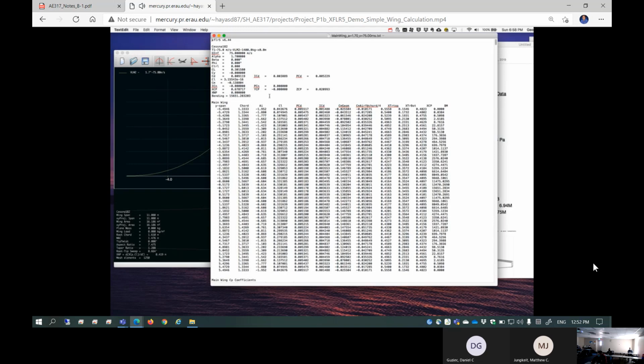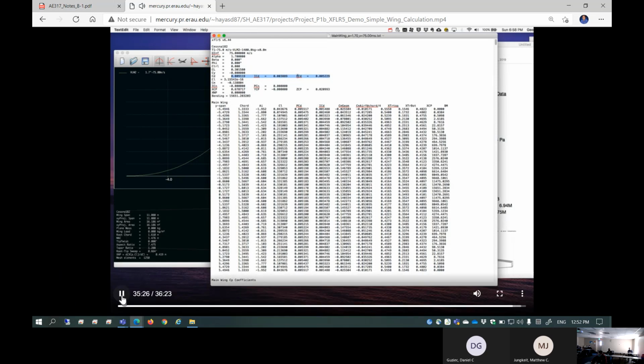And so I have similar information up here with those drag coefficients, induced and the viscous pressure drag, or this P stands for profile. So this is the computed data based off of how many panels you have. Suppose you choose the 3D panel method, and then if you choose to go for like 1 million panels, you have 1 million data sets coming up. Okay, so let's be careful about that.